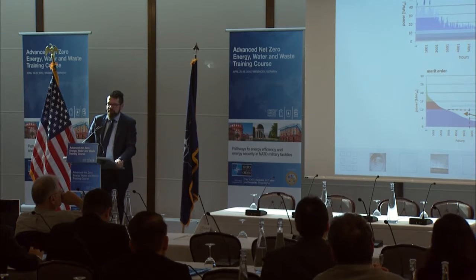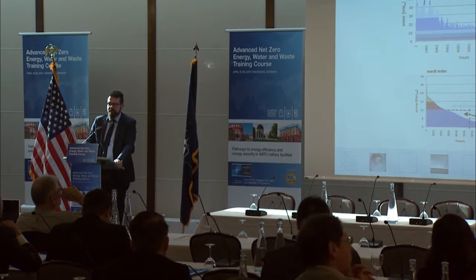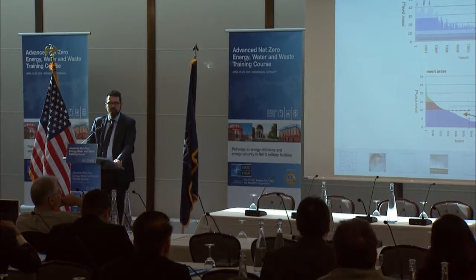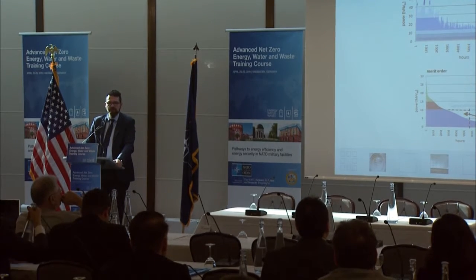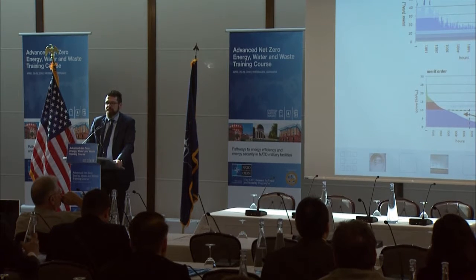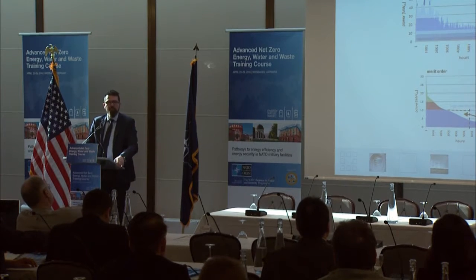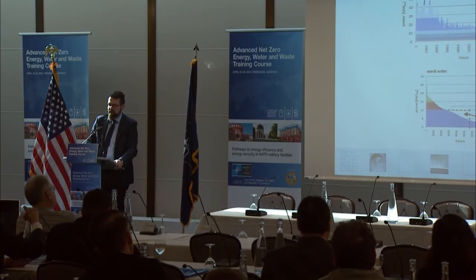But in this lower figure, we call it the load duration curve. You can see what is the highest load and what is the domestic hot water base. And then the different colors show which piece of generation equipment generates the heat you need for that. And then you can easily calculate the number of running hours and the amount of energy you need from this equipment and the amount of primary energy you have to put in.